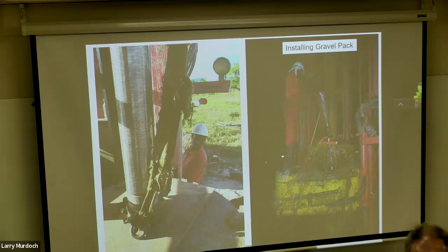So the common way of joining PVC pipe involves glue. That glue has solvents in it that are carcinogenic, like methylene chloride. So you don't create wells with pipe that you get from Lowe's with glued-together fittings. You use casing and screen like this with these flush joint threads. These are more expensive, but they go together and form a seal without requiring glue. There's a groove right here and an O-ring goes in there to do the sealing. So it screws together with an O-ring seal.